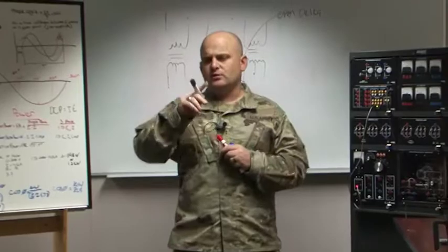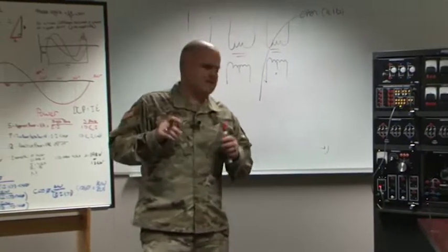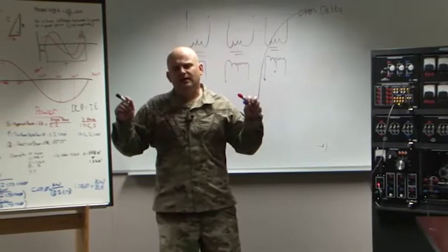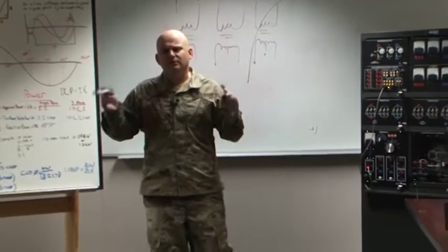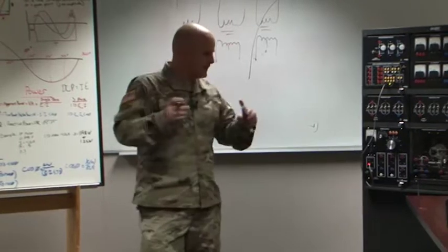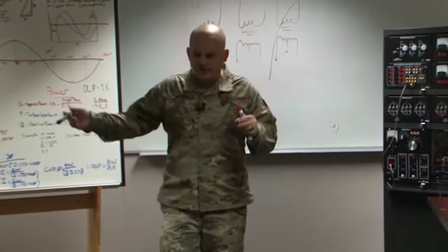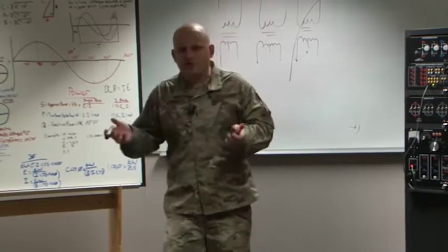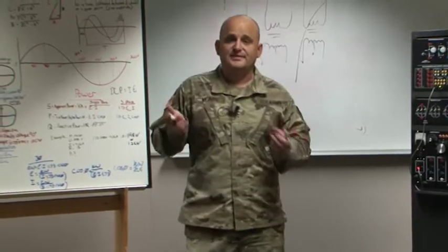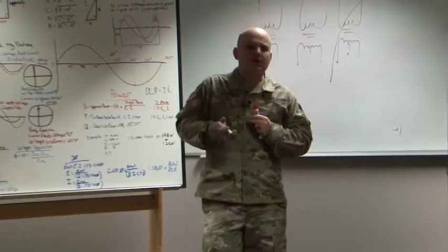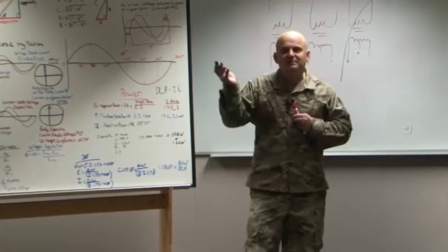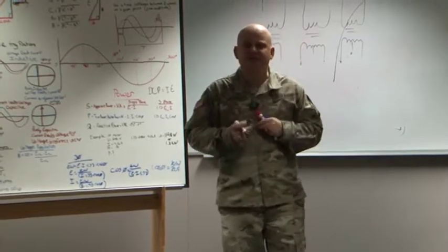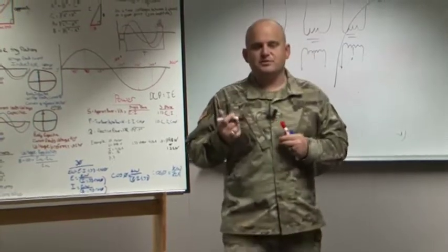However, what did you do to the equation? We go back to this wire, right? That wire that I had, and I said, if I add 2 of them, I get more ampacity, right? I can create more power in there. Well, if I take away a transformer, I'm taking away some material from that circuit, so I obviously have to be limiting some capacity of the system. But by what factor? What you're going to see is you're going to be limiting by a factor of what I believe is 57%. I think this is what the book said, 57.7%. And that is the inverse of the square root of 3.